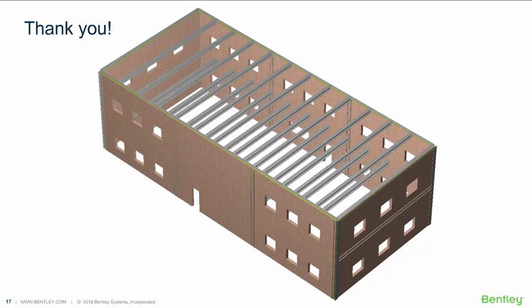Can you design the masonry shear walls with vertical chord reinforcing at each end of the wall, or are you limited to intermittent? No. You are free to do so. The software allows you to create vertical strips. You define vertical strips, and you can set them at the ends to carry most of the loads, and then in the middle, the minimum will be set.